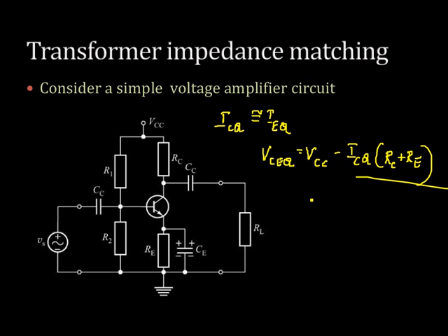So a portion of the supply voltage is dropped in the resistors. Now the DC power that goes to the transistor, what is the DC power? PDQ, the DC power that is dissipated in the transistor, is VCEQ into ICQ. This is the quiescent condition we are talking about. That is why this Q is coming here.